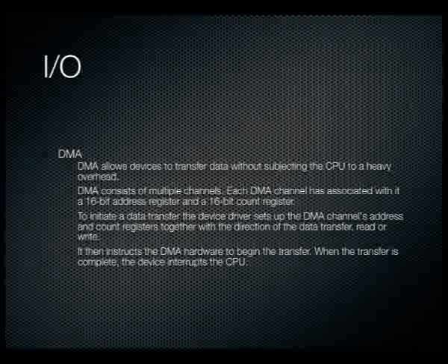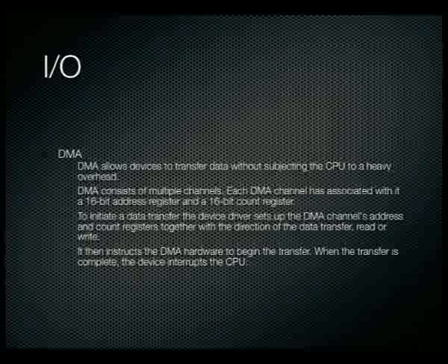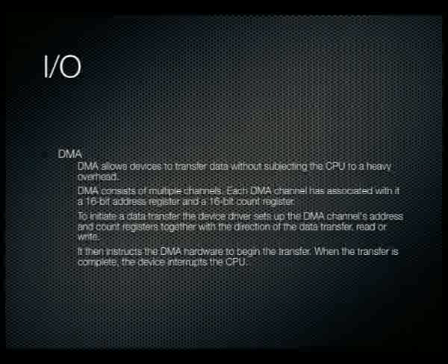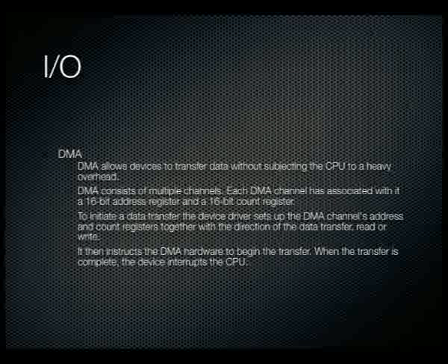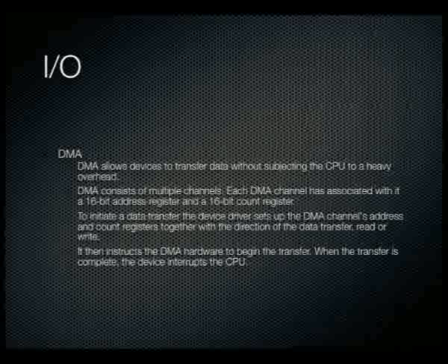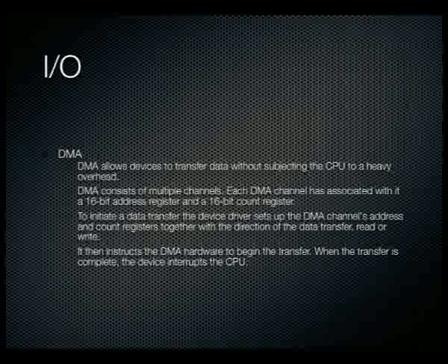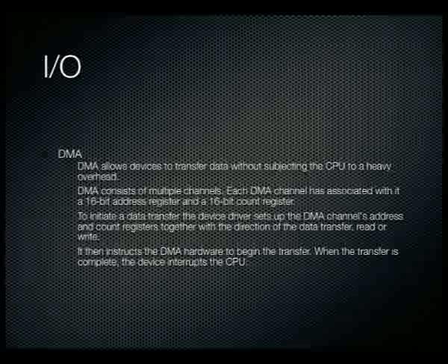DMA transfer is a good way of moving big chunks of data around without the CPU having to go load, store. You can simply set up the DMA to move it around in big chunks. A lot of microprocessors have DMA or eDMA subsystems that you can utilize to move big chunks of data around. Our processor, of course, doesn't have a DMA channel, but it is available on a lot of DSP processors.